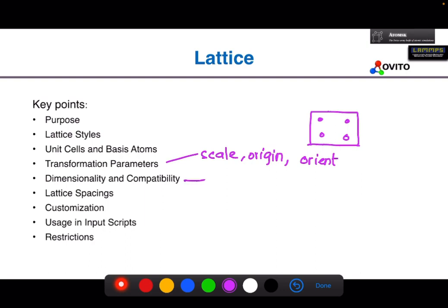So you need to keep in mind that, for example, at the beginning of this code we have used the code dimension 2, and in the later part, while creating your geometry, if you say that your geometry is HCP, which effectively means that you cannot make it a 2D material, so it is not compatible with what you said earlier. And you need to keep in mind that this dimension which you are working with is compatible with the first part of the code.